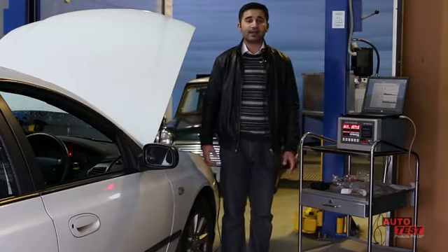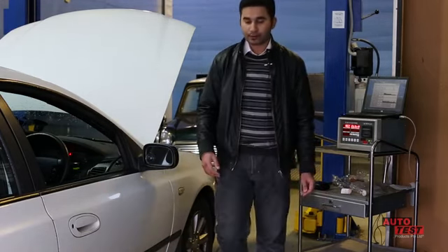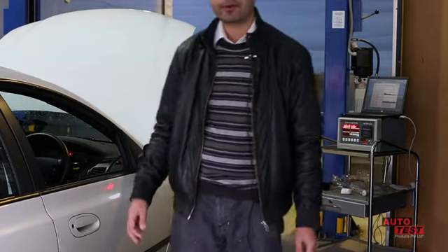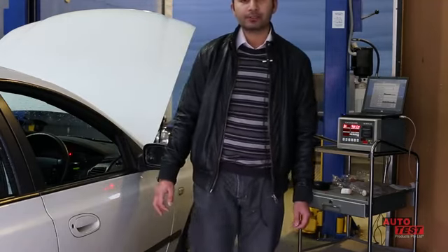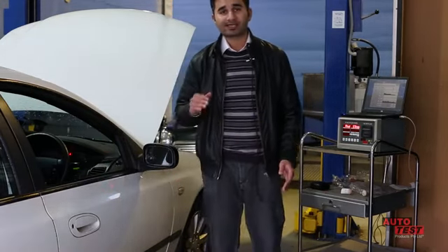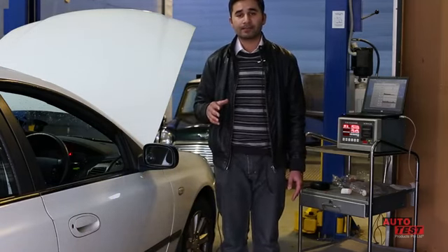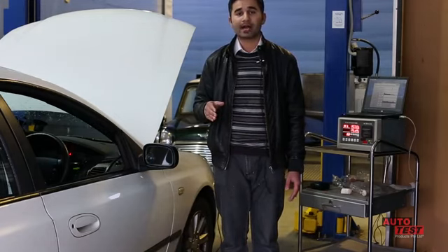In this phase, when it says fully depress the accelerator, we're going to sit in the car and accelerate the RPM to about 2500 RPM. When we accelerate, we'll accelerate immediately and then release the accelerator immediately to let the RPM settle at idle.